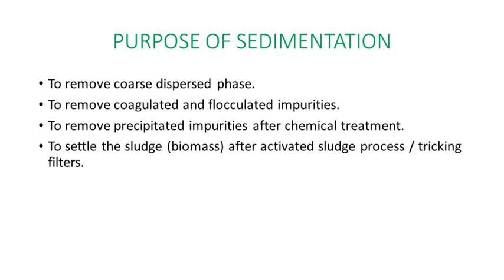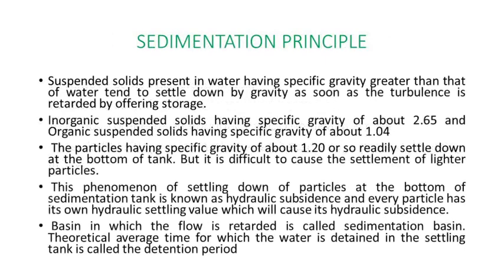So these are the various purposes of sedimentation. What is the principle of sedimentation? Basically, the principle of the sedimentation process is that the suspended solids present in water have a specific gravity greater than that of water and tend to settle down by gravity as soon as turbulence is retarded by offering storage.